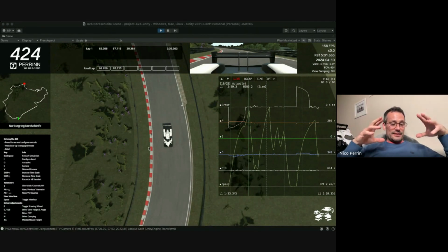Some systems that I know people are talking about, having one motor per wheel, are too heavy for us. One problem with that, of course, is that it allows left to right torque vectoring, but we don't really need it with 4x4 because we do front to rear, and that's powerful enough. The problem with one motor per wheel is when you're limiting your torque, because suddenly your maximum torque becomes limited.